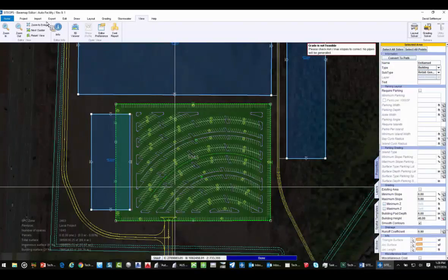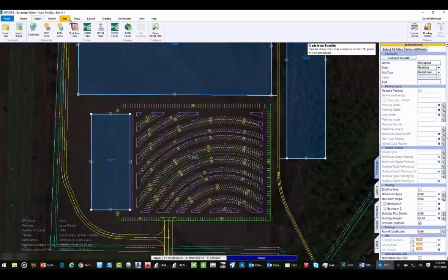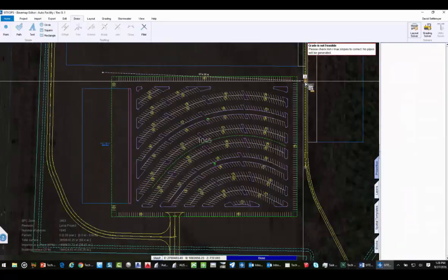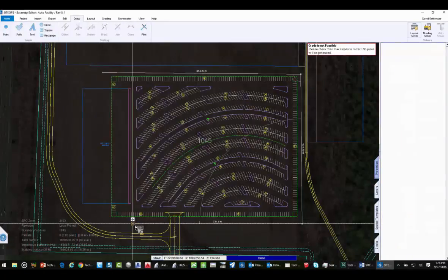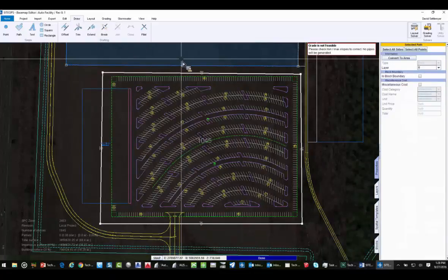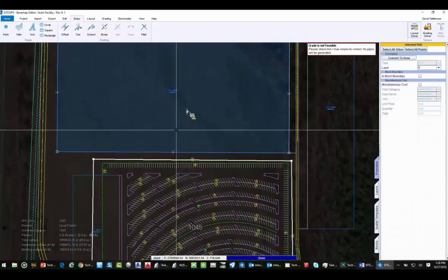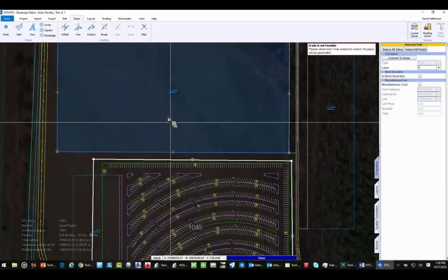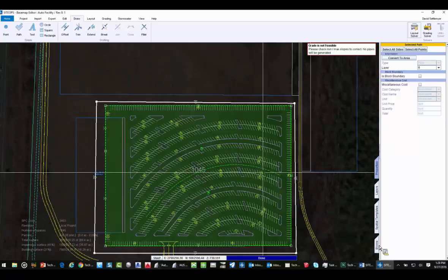But one of the things we created, and I'm just going to do one really quick so you can see it, is we have the ability to import LumenRT items, and you can do SketchUp as well. You can bring in their blocks. So if I had somebody doing a SketchUp, a Revit, an ABD building, bring that in as a Collada file. I can sit over top of this and make it look like a real warehouse, a real manufacturing facility. But what I'm going to do is go into blocks.